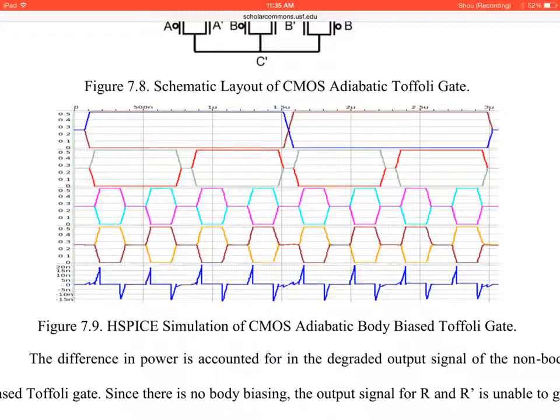But if you have one or the other, it's going to have a different output power consumption because one of them is on and the other one is off, right? So you're going to get different power spikes, and you're trying to make it as consistent as possible. If you get a large enough circuit, you saw process variations, you saw voltage variations, right? So if you get power spikes that are large enough and you know how the circuit works, you actually are figuring out what the cryptographic key is.